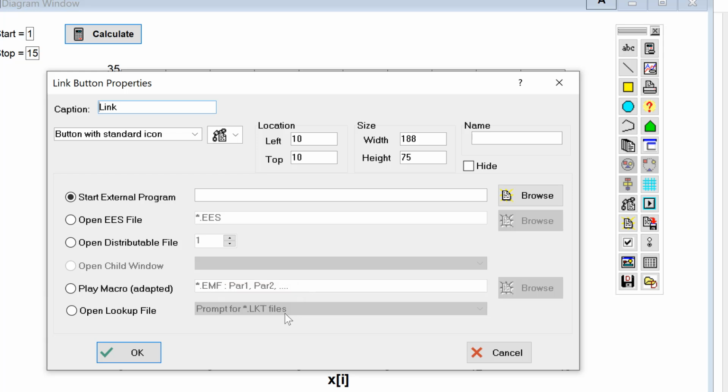And then what will happen is when the macro file is played, the macro file is going to look for the sequence %n, where n is an integer value, and it's just going to substitute in that list of variables that you sent to whatever macro commands have that %n. So for example, anytime it sees a %1 in the macro file, it will replace that with whatever you sent it. So it's a nice way of communicating with that macro.